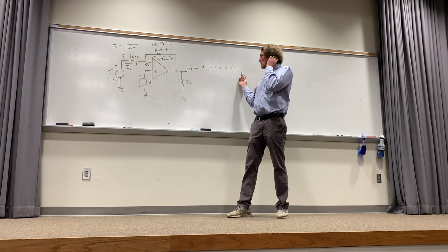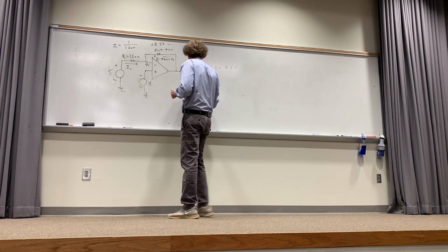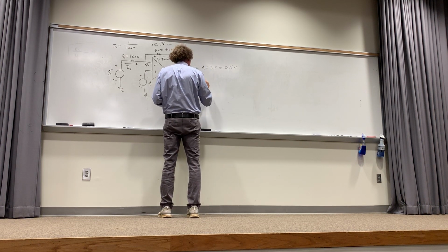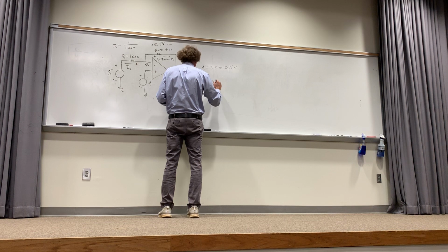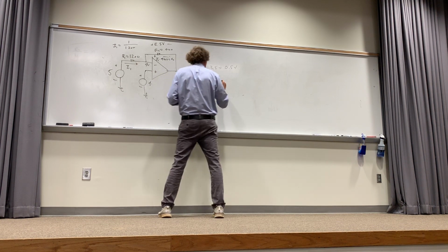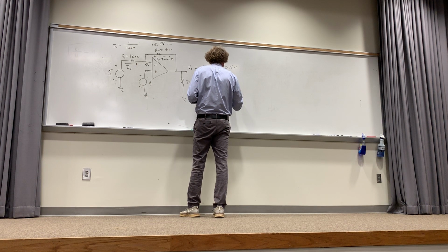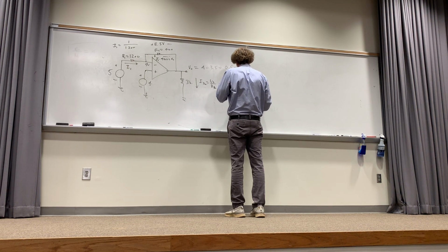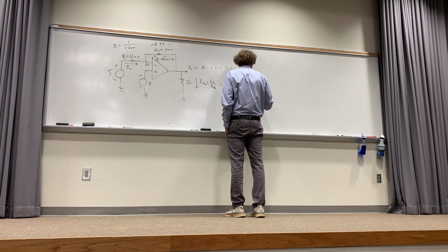Now, once I have that voltage, if I want this current, what does it become? That current, I3K, is just equal to V0 over RL, or 3K. So it's 1/2 divided by 3,000, or really it's going to be simply 1/6 of a milliamp.